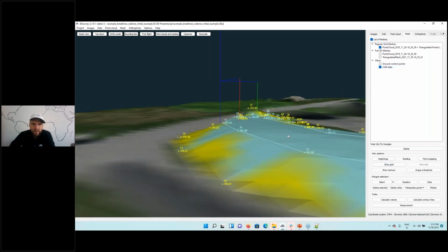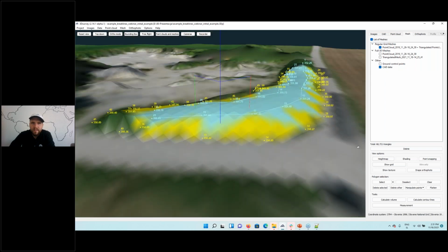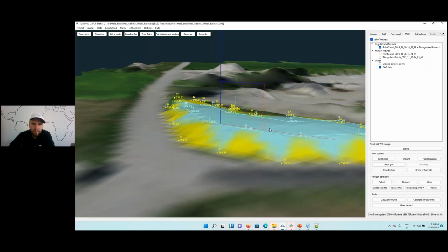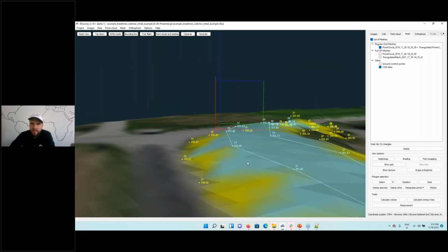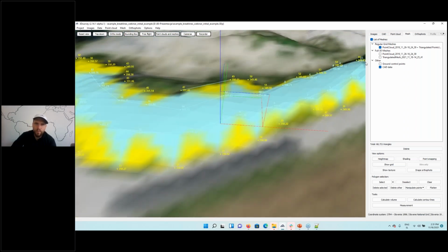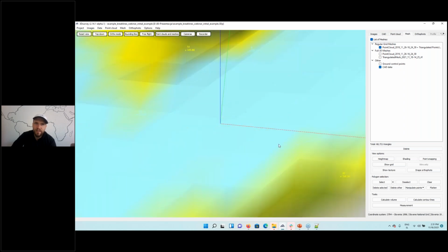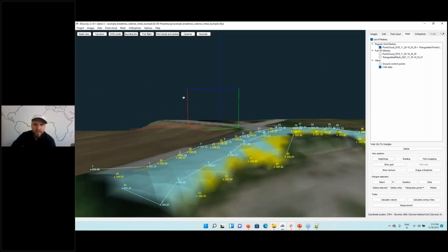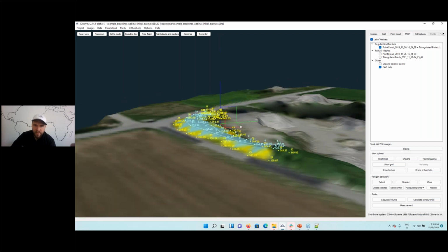And this is how we can now combine the data to make more realistic point clouds even for areas under the forest. So the things that were not possible before with photogrammetry only. Here we showed how to join in the points measured with total station, but these points could be measured with any similar technology. We could also achieve similar things if we added just LiDAR data for this area. Okay. So this was example number 2.